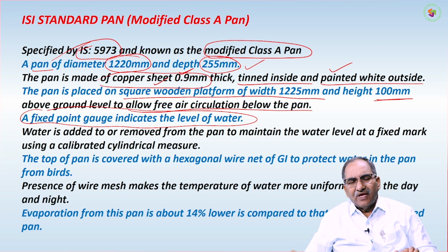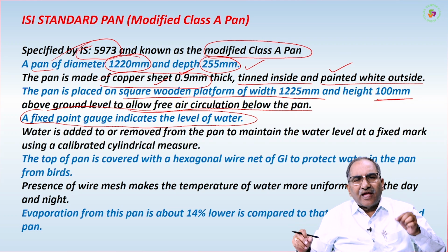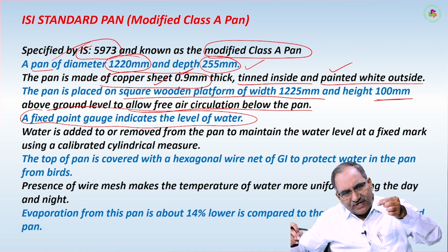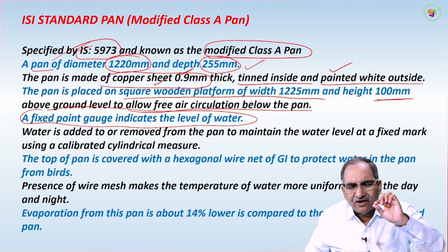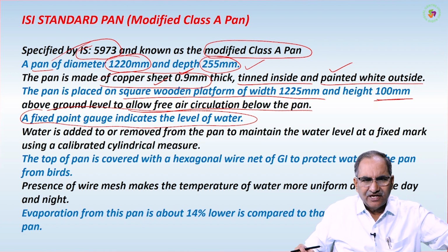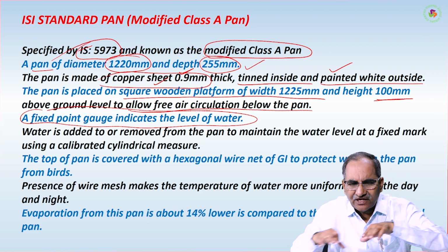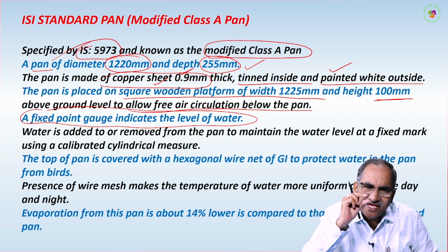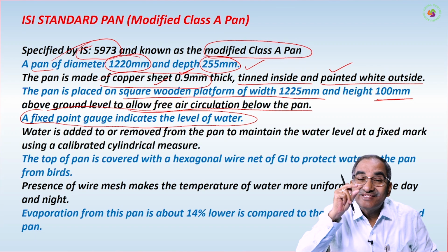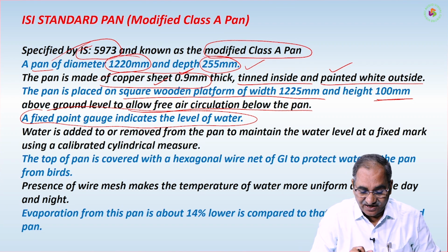What I will do actually, next day again to fill that, the water level decreases because of evaporation. How much decrease has occurred I will see, and basically again I pour water to that level. So that decrease in that height, that is what we will say mm per day, this much evaporation has occurred.